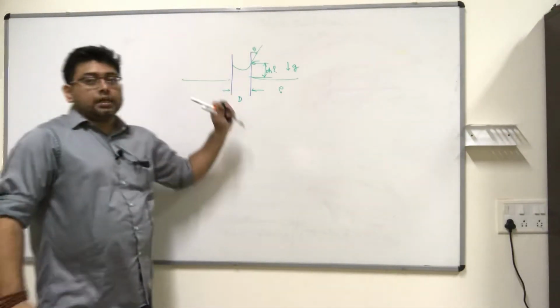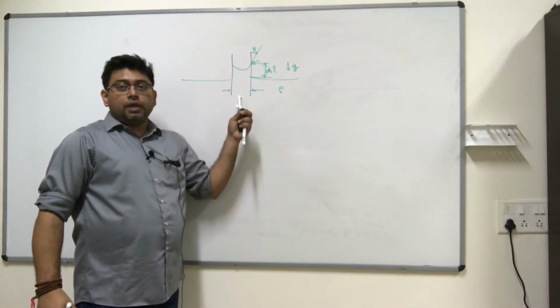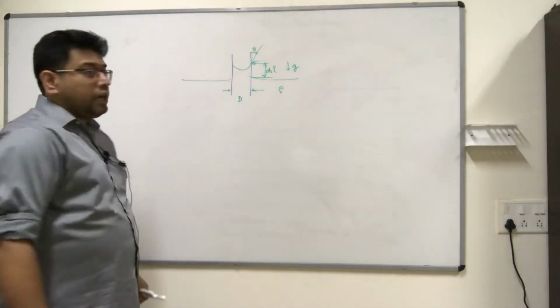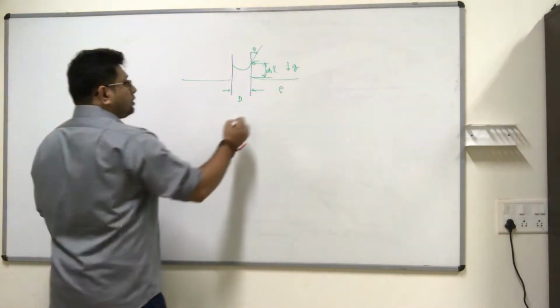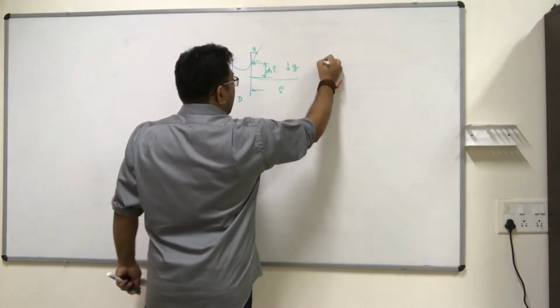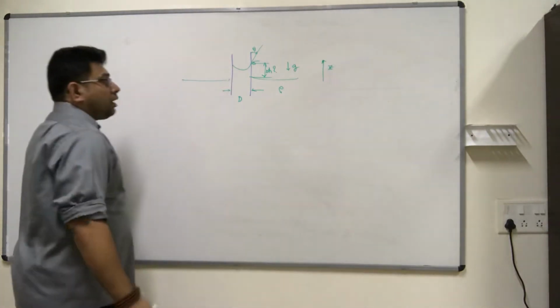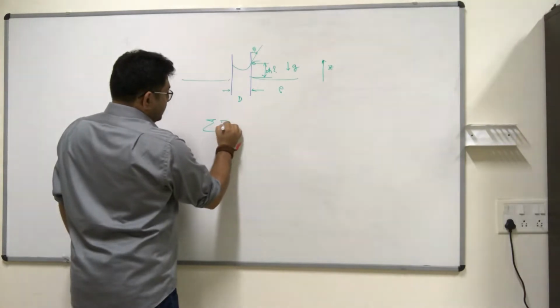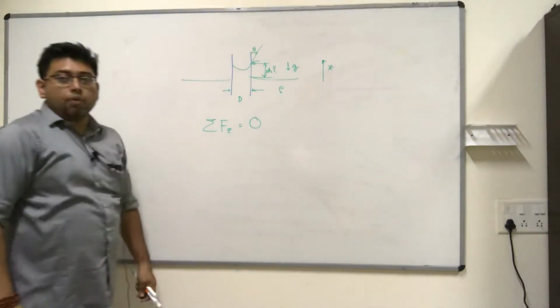And the reason I selected this problem for you is because it's a very beautiful example of a problem involving surface forces and volumetric forces. So this is a fluid in statics condition. So let's say the Z points in the upward direction. The net forces in the Z direction have to amount to what? They have to amount to 0.